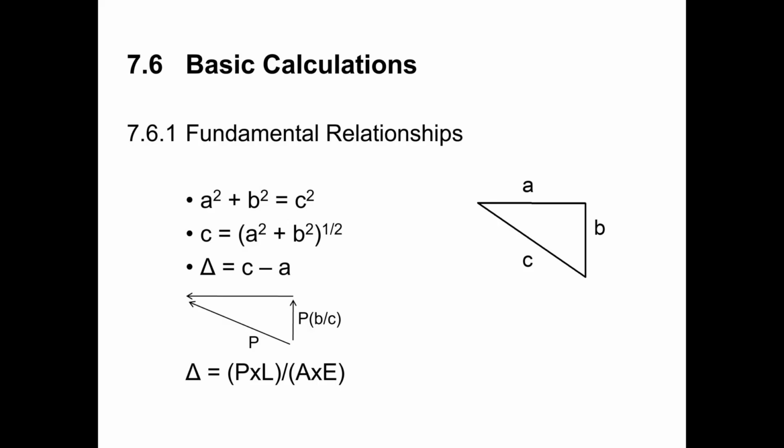Okay, we have one. Why does the moment capacity for straight strand have a bit of a slope at the ends of the beam? Yep, that's a good question. We don't get full moment capacity until the strand is fully developed. And so that little slope at the end of the diagram is just to represent that as the strand gets developed, it has more and more capacity. And then once it's fully developed, then we have a consistent and level capacity. So good eye. That's why there's a little bit of a slope right at the end of the beam. That's the development length of the strand.